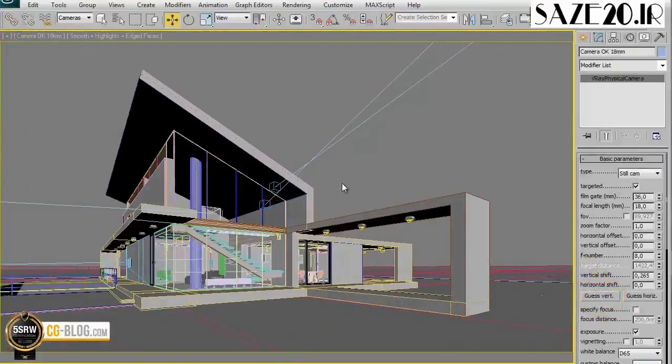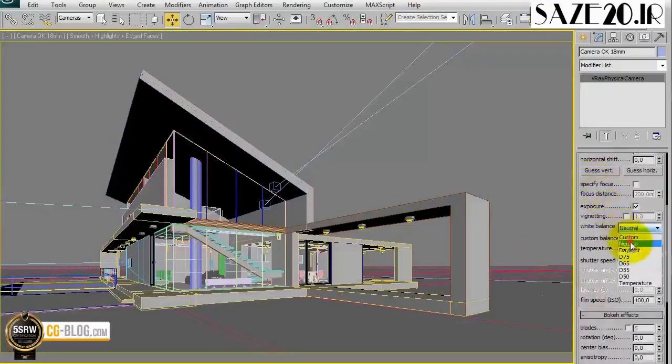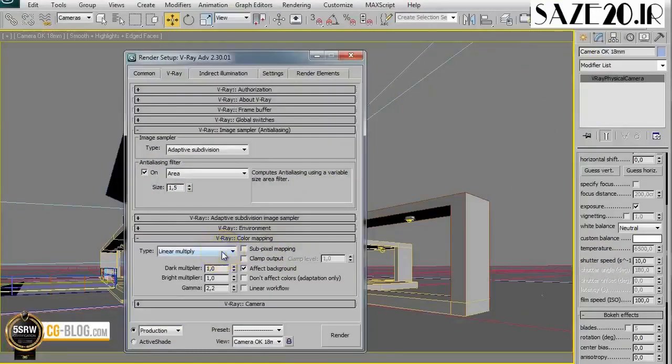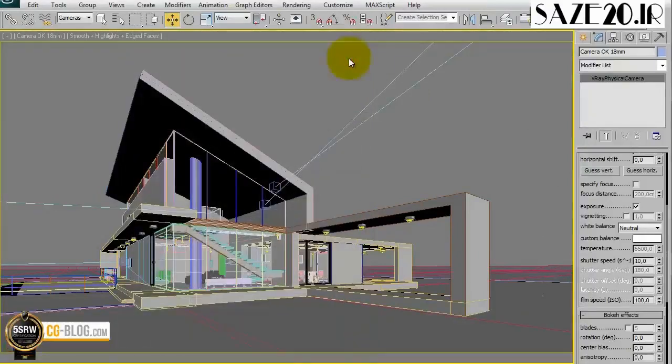To complete step 1, let's see how to set the exposure of the V-Ray physical camera. In situations such as this, I mean in the exterior night, we will set, as a standard approach of the method, the shutter speed to 10, that is a value consistent with reality, since in this case we are in low light conditions. Finally, given that we have light sources near the walls, and this could create some problem for our image, we will use the color mapping exponential instead of linear, so as to avoid a large overexposed area on these walls.